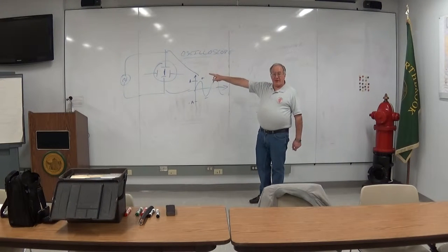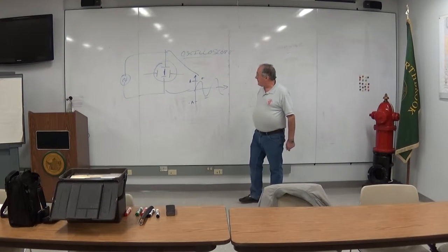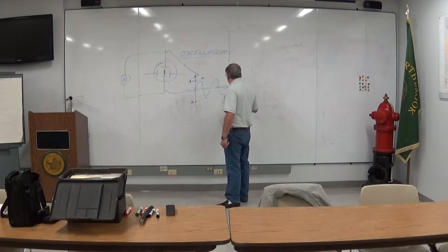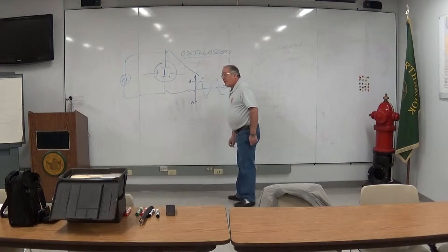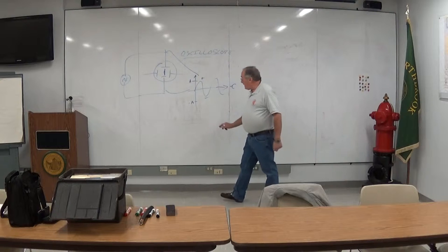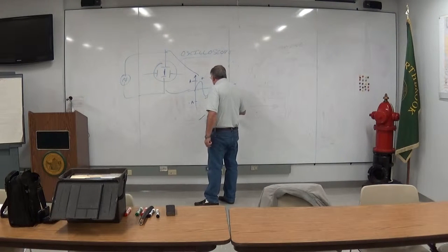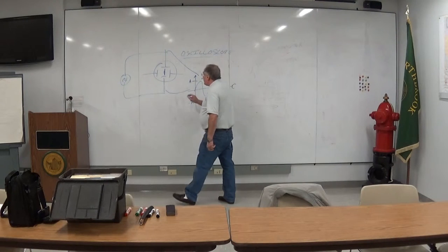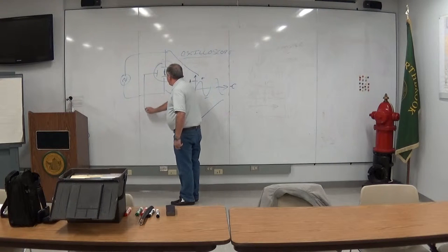But all you'll see is a vertical line. So how do you make it look like this? Well, what's going on here? This is time. Time operates at a constant rate. So what I need is something that produces a ramp-up voltage between these two plates.